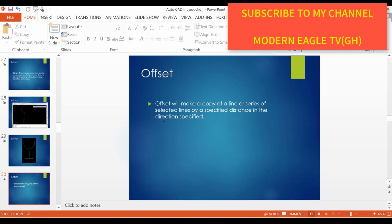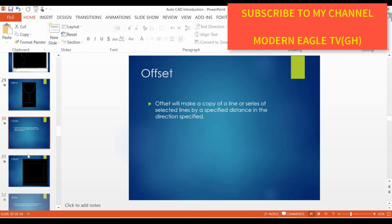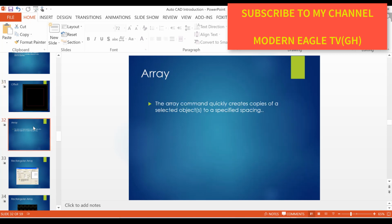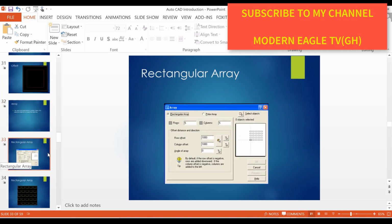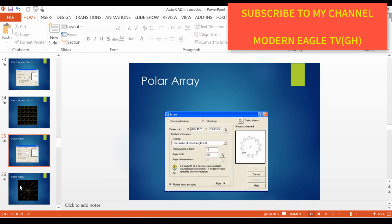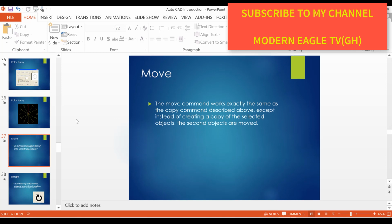Offset. Offset will make a copy of a line or series of selected lines by a specified distance in the direction specified. See this example of an offset object. Array. The array command quickly creates copies of a selected object at a specific spacing. Rectangular array. This is an example of a rectangular array. Polar array. This is an example of a polar array.